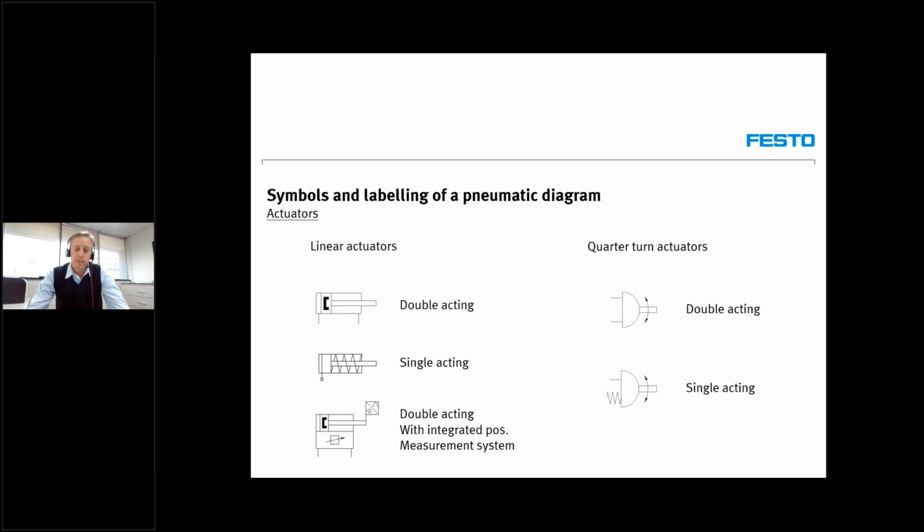Yeah, you're 100% correct. We've got little digital pressure gauges which have specifically differential pressure inputs. And as you mentioned, it's very easy to connect that across the filter and send the signal back to a PLC, which will give you an indication whenever something's wrong.